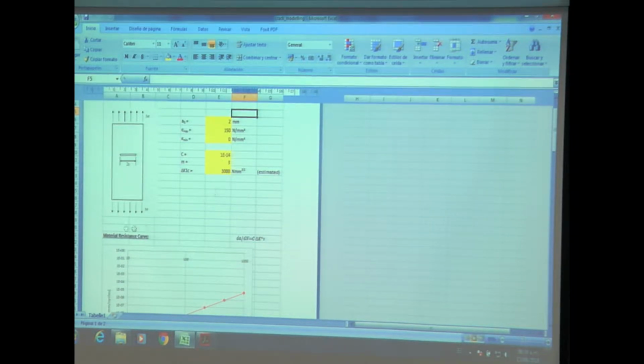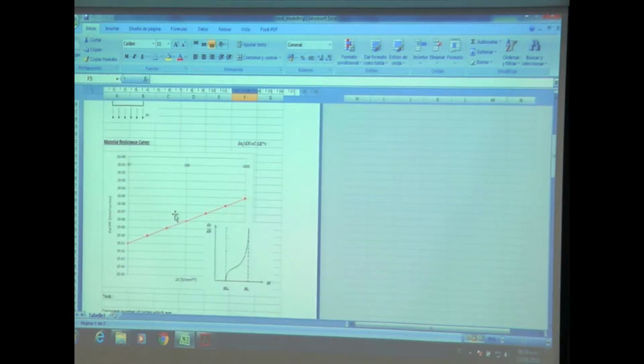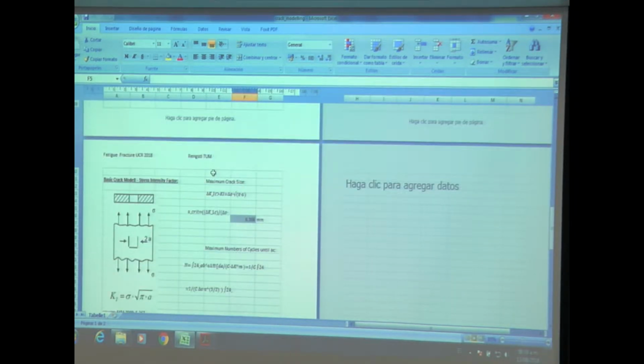And at the end, you see here the definition of our section 2, so of the crack propagation. And by using our formulas and turning around the equation, you can calculate the crack length. So the length would be here 6.4 millimeters.